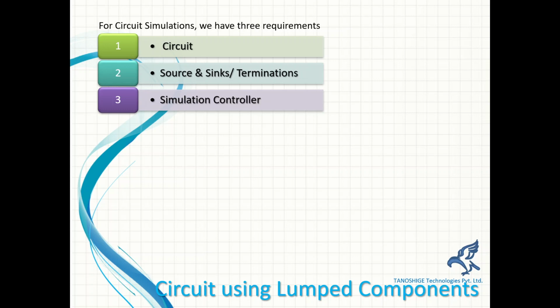Each schematic can support multiple controllers, but then the results are going to be nested, right? So you should be able to parse the result out of it. So it is recommended to use only one controller on a schematic. Now if you want to do another analysis, just make a copy of that schematic and change the controller, right? So that's the way to do it.